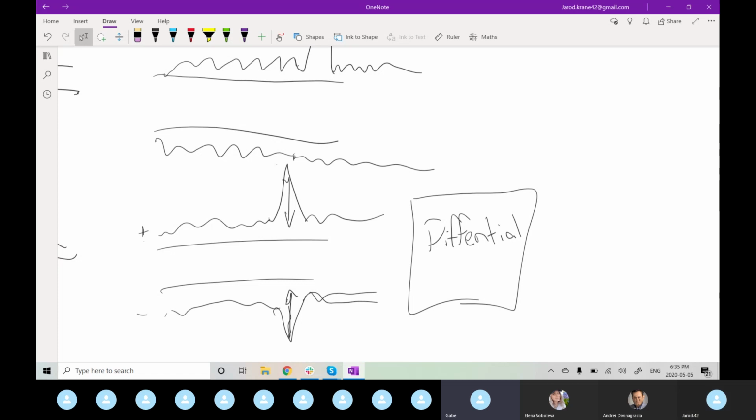Are those two peaks the noise, or is it the signal? That'd be the signal, sorry. Yeah, so if noise is induced, it'll peak the same on both, and when you take the differential of that, you'll be able to flatten it out.